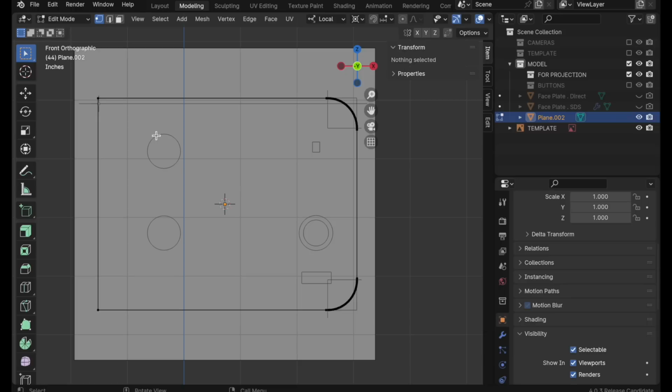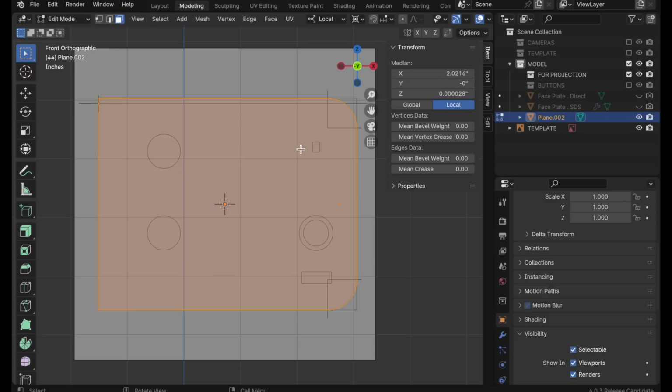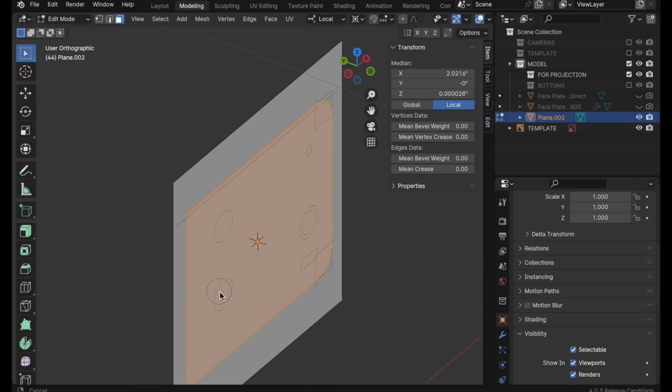Now, we need to start adding details for these cutout areas. Buttons actually sit over these areas, but they are cutouts still. And we need to remember that ngons, this is one big ngon. We need to dice it up into smaller segments because remember, if you try and create a hole in an ngon via the knife project or a Boolean operation, Blender is automatically going to create a connection to the outside perimeter, and it would be better if we controlled how that connection is. But we first need to move this geometry into position.